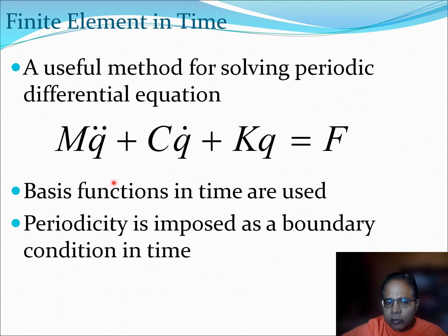Now, what we are going to do to solve this equation is we are going to consider a time-based discretization of the solution. So we are going to use basis functions in time in a manner very similar to how basis functions in space domain are used in the classical FEM method. We are also going to impose periodicity on the solution as a boundary condition in time.